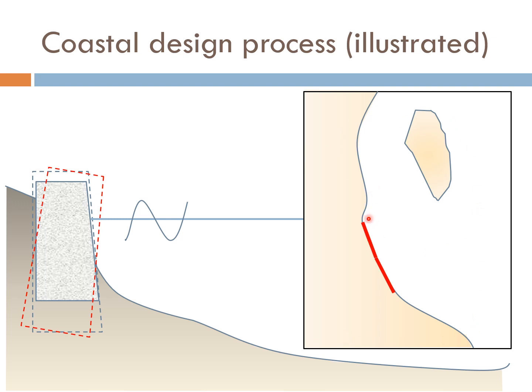Now, if we are going to construct a hard structure here, then we also want to find out whether this section of the coastline has a good foundation. So that's where the SI, site investigation, may be required to be conducted. Now, let's say at the end, the engineers decided that they need to build a seawall like this on the shoreline. This is the beach profile.